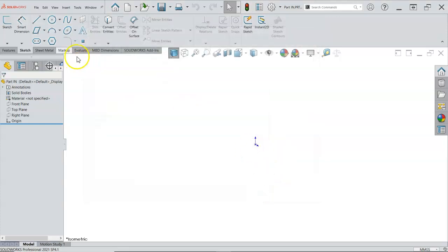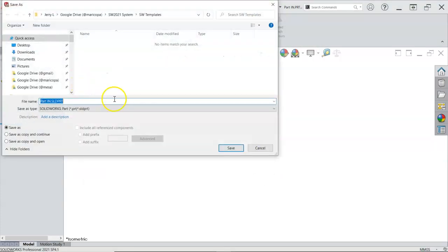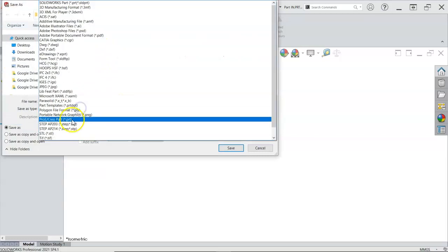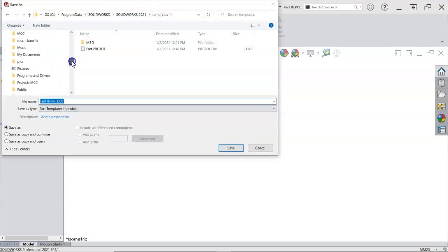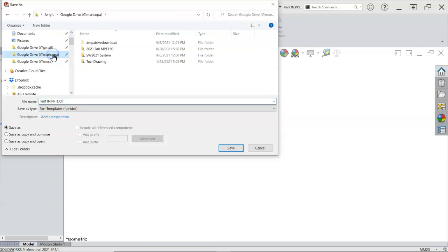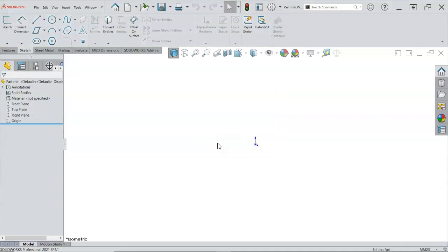So I'm going to hit OK, do a file save as, find my part templates. Again, it's going to automatically default, and that's also if you save something there in that lower level, then you'll want to be careful that probably the next part that you create, next assembly, next anything is going to also try to go there. So I don't really like the capital mm. I should probably change that to lowercase in, but we'll go with the millimeters and then have my settings.